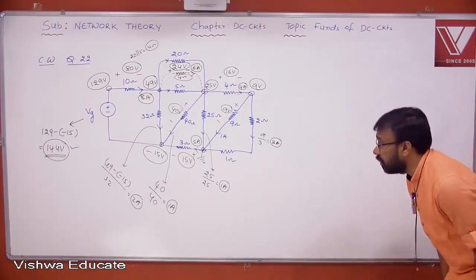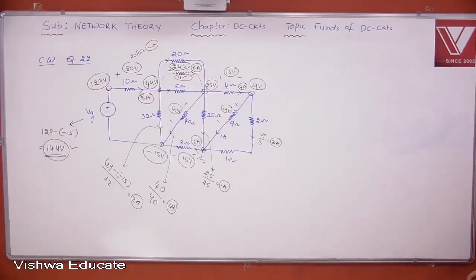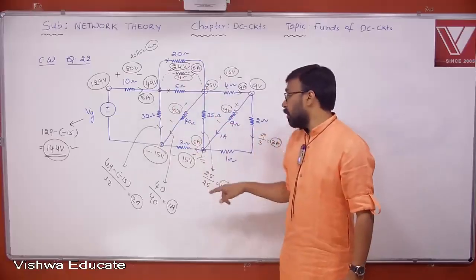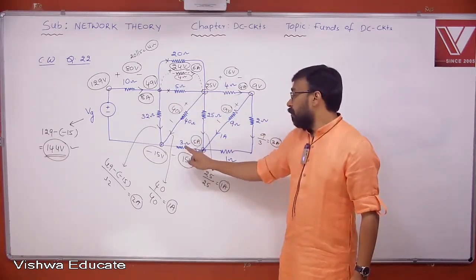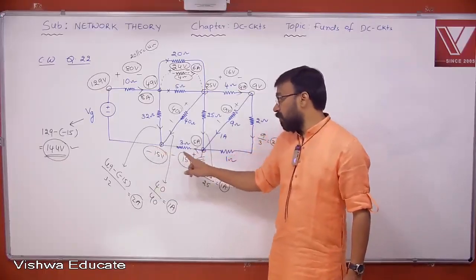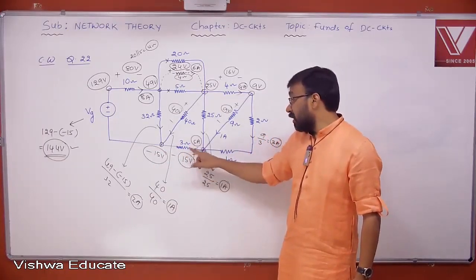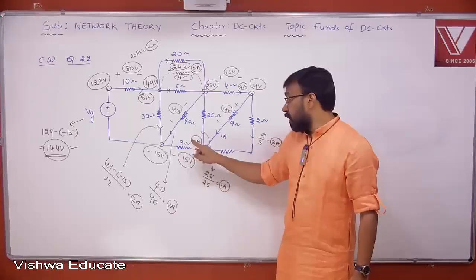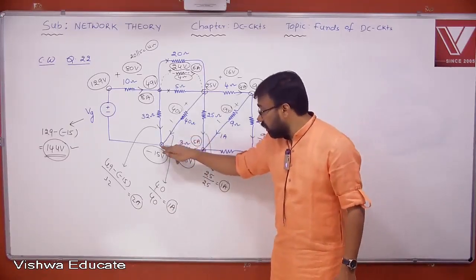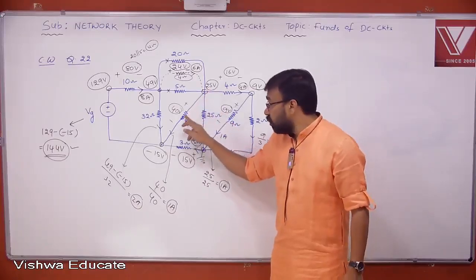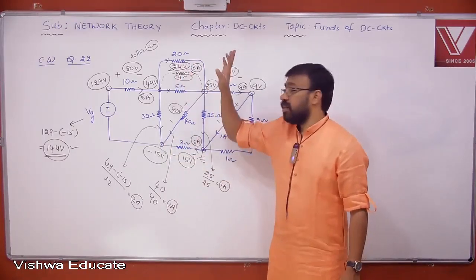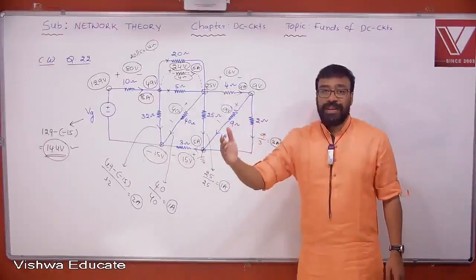Please, quickly note down. The most critical point or crucial point in this entire problem is what? This one. Most of the people make the mistake of taking 0. They always take everything as 0, but that is not possible because there is a resistor in this particular context. You cannot take it like that. You need to find the voltage here, definitely. Then only you will come to know the current here. Then only you can find the voltage here. The sequence must be very clear.